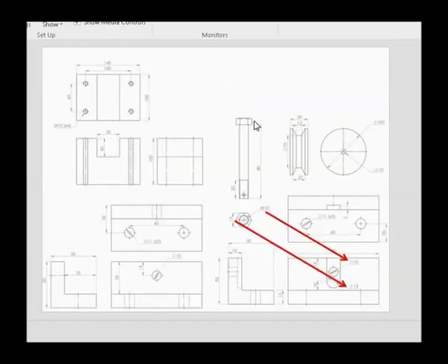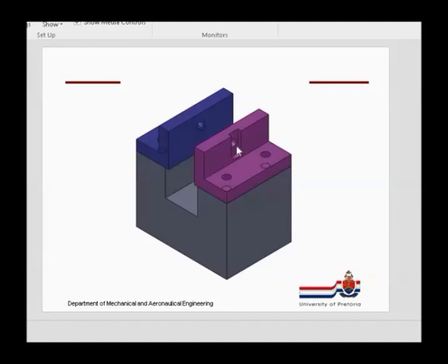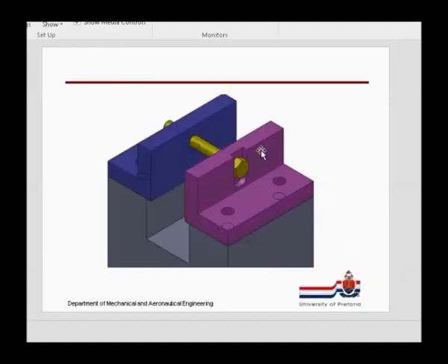Next thing would be that this bolt of ours has a head size of 15. This groove in the one L-shaped component has a width of 15, diameter 10 from the M10, and this diameter of the hole, which is also 10, corresponds. So I can actually put the bolt through this hole all the way through.